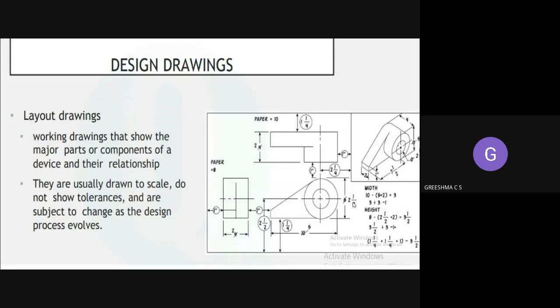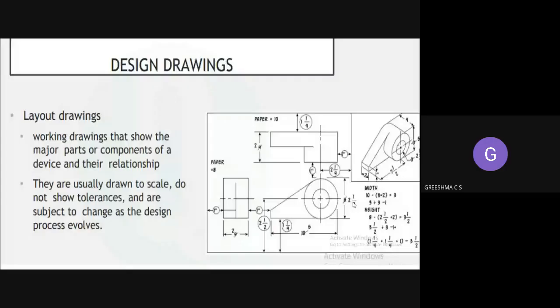you would have drawn in a layout a site plan. Site plan. So first, what will we be doing? Site drawing. First, there will be a plot. Inside the plot, you will be showing your house, the plot will show, the nearby road will show. That is the major components you're showing. You're not showing the house in detail. You won't show the plan or things inside that house. You will just show the major components. That is, first one is a plot. Next one is telephone line.